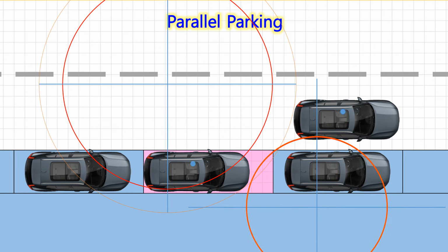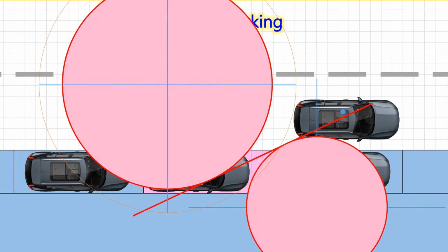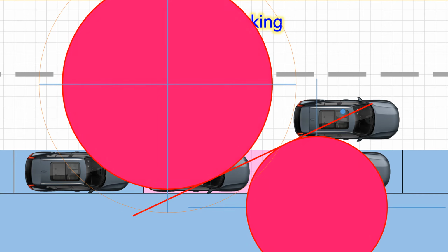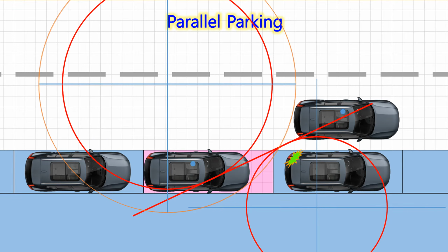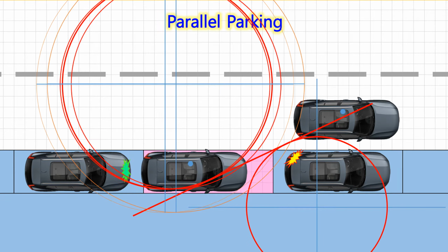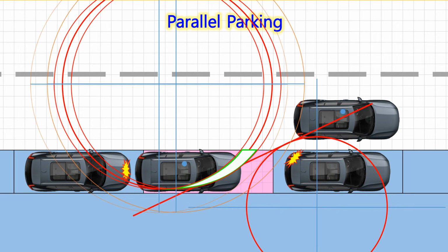During the parking process, on the basis of the right rear wheel, 2 minimum turning circles and a straight line tangent thereto were utilized. Since the steering wheel is turned all the way, the right rear wheel cannot go further inward than this boundary. If there is more space available in the front and rear of the car, as a tolerance, this is the green zone the tangent line of rear wheels can go to. Since it can be seen graphically by utilizing the principle of rotation in this way, we can see how narrow the tolerance is given and also where the green zone is in some shape.